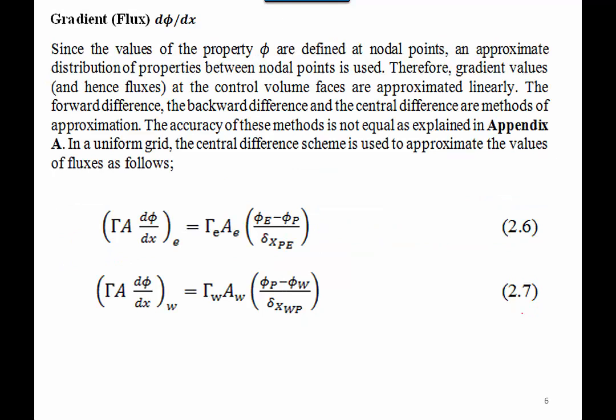Now we will talk about how we calculate the value of the flux, d phi by dx. As we said before, since the values of phi are defined only at the capital letters, which are the nodal points, we have to implement an approximate method to calculate such value. An approximate distribution of properties between nodal points will be used.